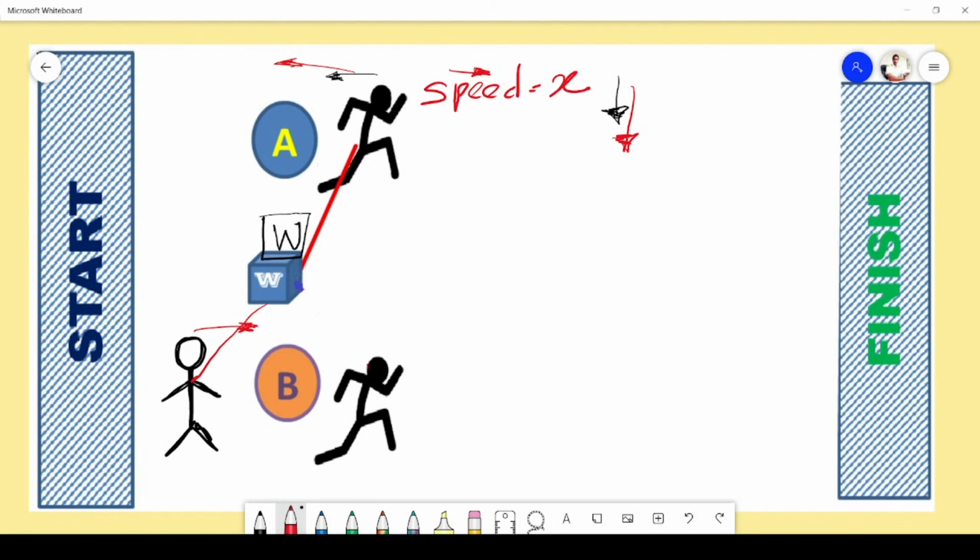We can see this scenario in the generator also. Suppose this is the running generator. If the generator is running and the other generator's frequency is not high enough, what will happen? The bus bar frequency also gets affected, because this incoming generator will suddenly accelerate as the load pulls that generator into synchronism. We can do a much smoother load transfer like this: suppose we keep this incoming generator at the same speed x, and then we connect this load.